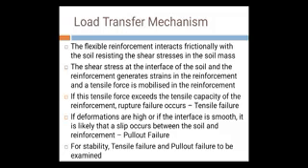Because in the friction there will be stresses, which are tensile stresses at the surface. So to restrict that, soil reinforcement should be there. If this tensile force exceeds the tensile capacity of the reinforcement, rupture failure occurs, that is called tensile failure. Obviously, whatever material we use, if the force or stress goes beyond the capacity, then it may fail, that is called tensile failure or rupture.